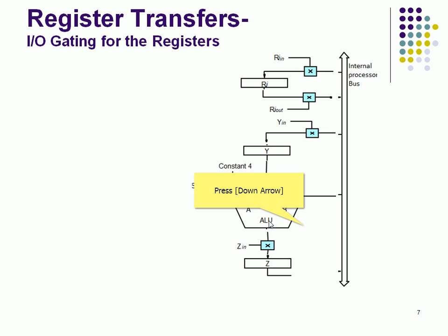Once the Z register holds that data, a Z out enable is essential. When Z out enable is performed, only then will the content of the result, the Z value, go to the general bus, that is, the internal processor bus. Otherwise it will stay at Z. Let us assume Z out enable; then the content of Z will be moved to the processor bus, right?